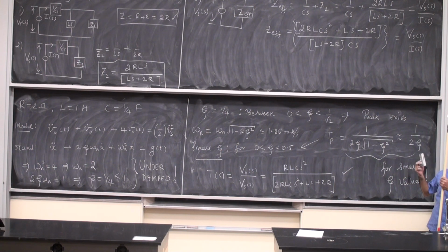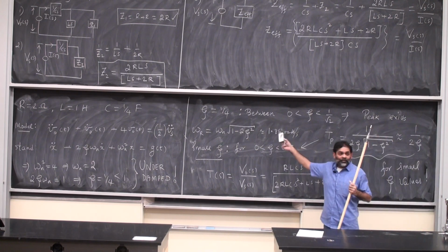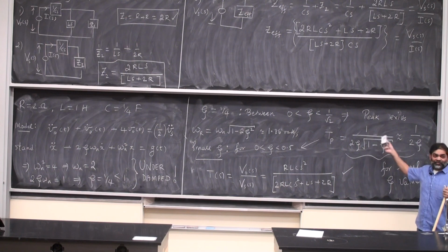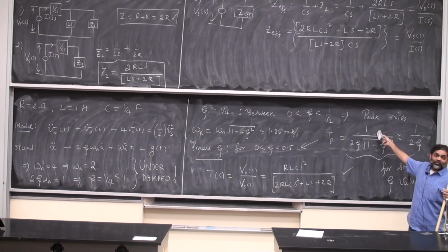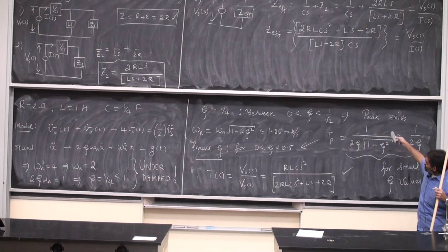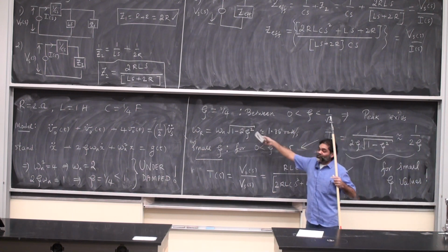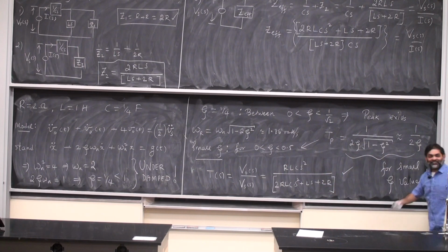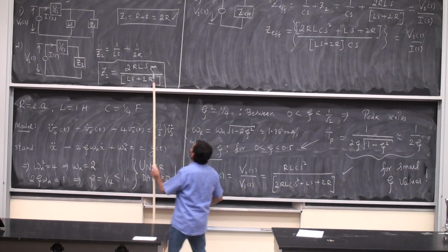And if you go beyond that, then you get omega r to be 0. So if your omega r is 0, then this does not necessarily have any meaning. It's not as if this goes to infinity. This goes to infinity when zeta is 0. But when zeta is 1 by root 2, you no longer have a resonant frequency. So the physical limit is boxed in. All right.